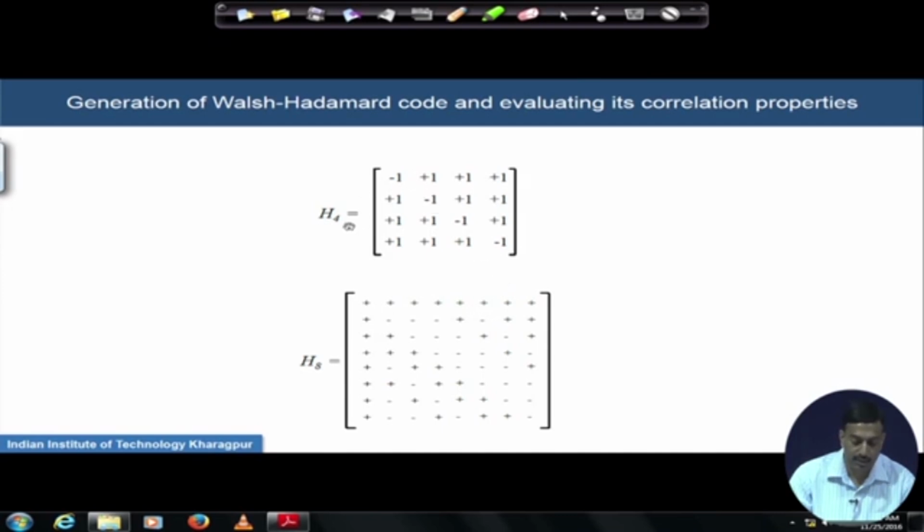but here we see that we have a special case where the first row is not all ones, but is a particular sequence. This of course is a special case, the only known case of a cyclic circulant Hadamard matrix. In general this first row will be all ones, and it will not be used as a spread spectrum sequence because it serves no purpose.